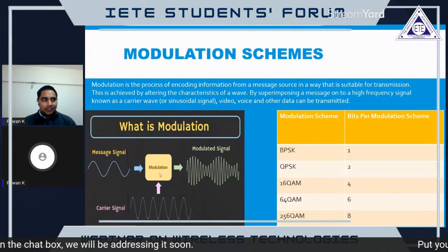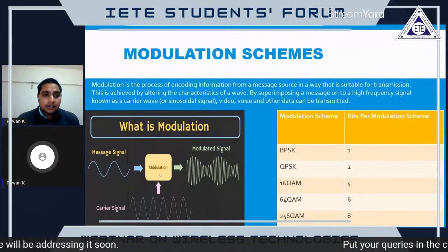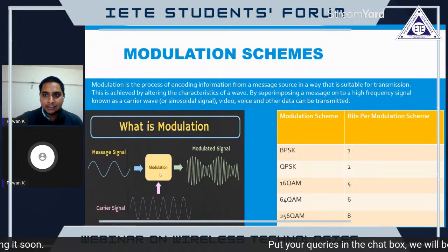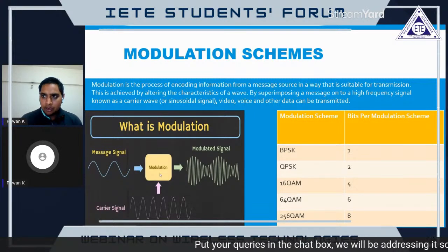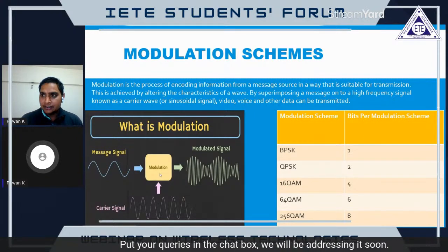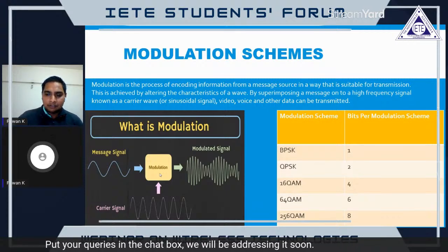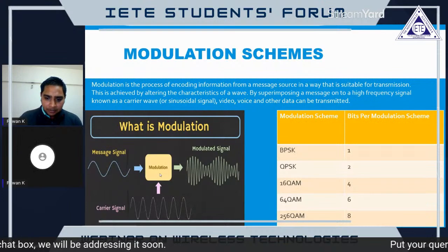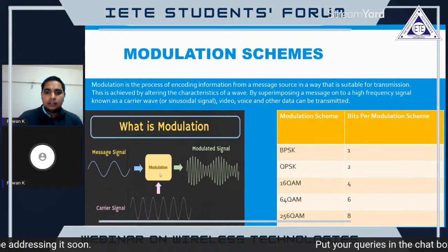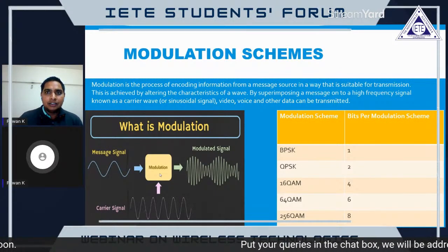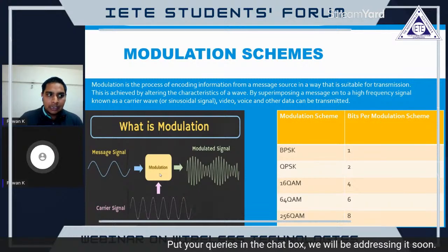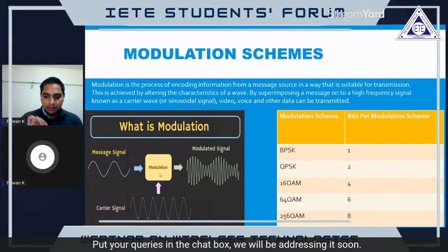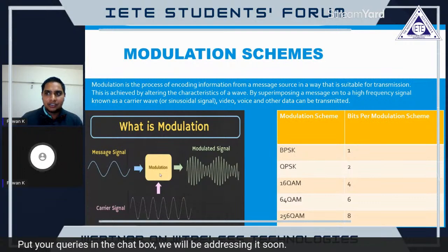The transmitter needs to send some energy signals. Here we can understand it with BPSK. We will take an example of BPSK and later you can extend it to other modulation schemes. In BPSK, only one bit will be sent at once, and one bit will have one symbol of the information.